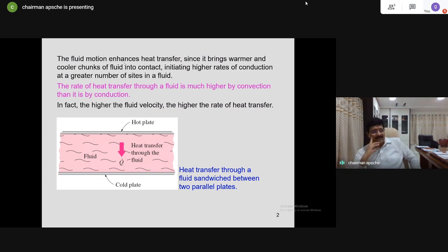In natural convection, the convection currents are basically because of the buoyancy effects, temperature gradients. The heated molecule should go up and colder molecule should come down. And again, this is controlled by various parameters. For example, viscosity. Now I have air in the room, and you have viscous fluids in the room, like castor oil or lubricating oils, etc.